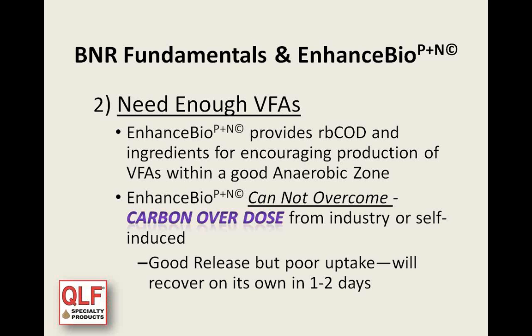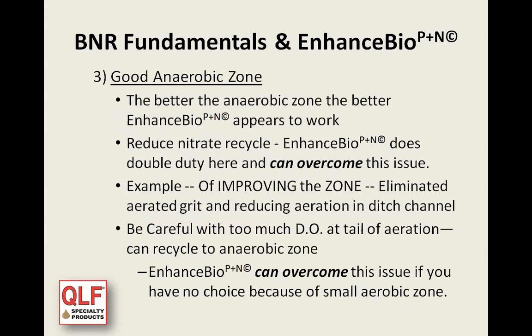We'll talk a little bit more about this later in the presentation, but what happens is with a carbon overdose, you get a really good release of phosphorus in the anaerobic zone, but it takes 2 to 3 days to get the bugs to recover from that release.